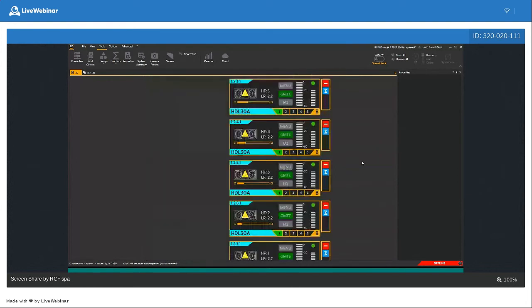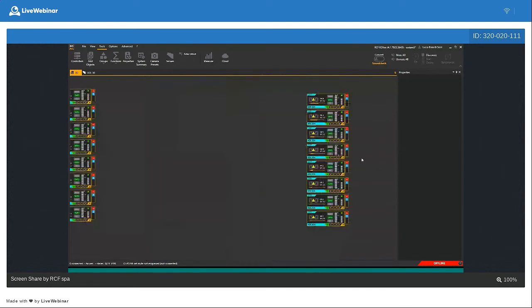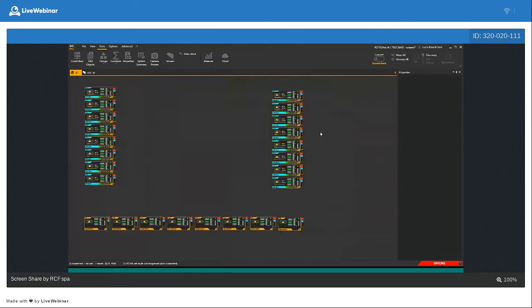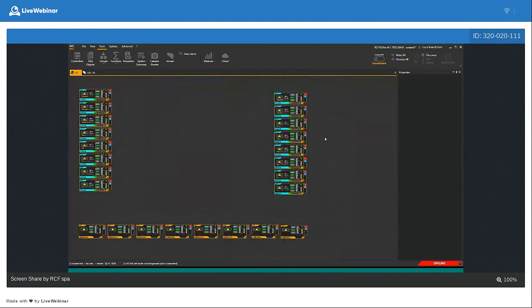So this is more or less the workflow. Of course, there are several other things that we could do, but before doing some measurement, I would like to show you how to manually make a cardioid preset of subs, and how to work with the cardioid preset, doing real measurement.